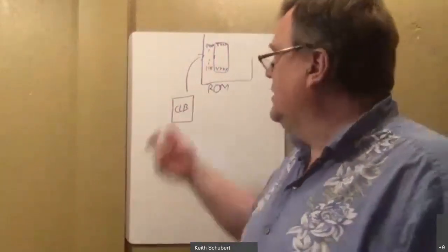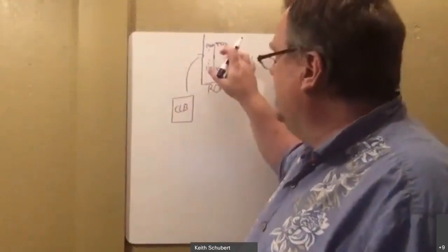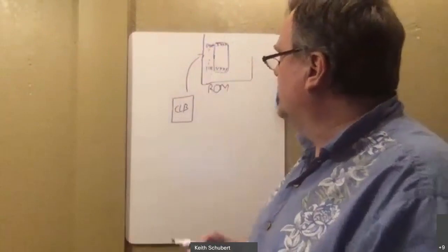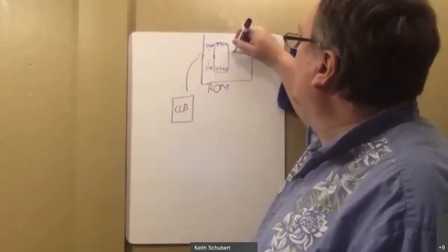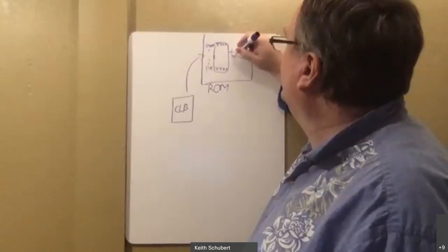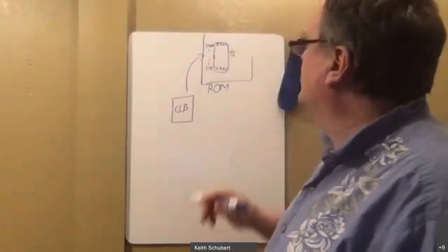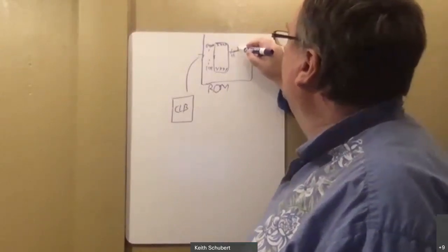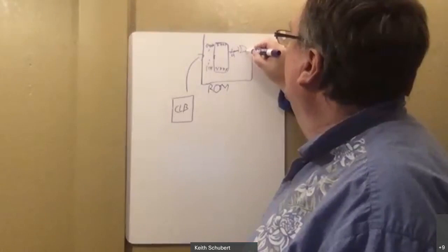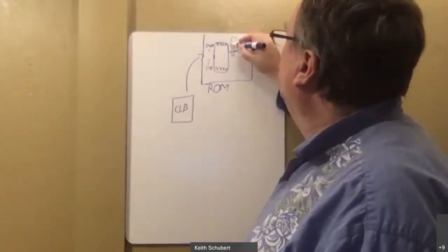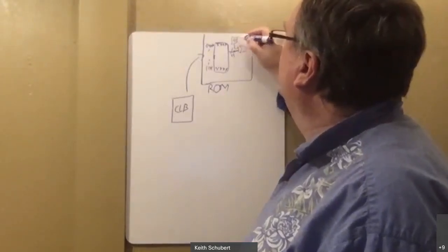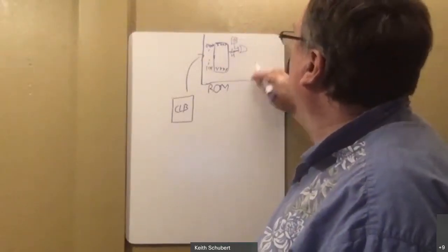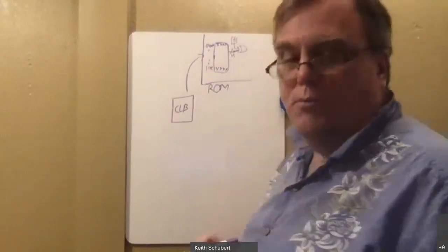It basically takes all the things, calculates all combinations, and uses the inputs as an address, and stores them all. Right. The output of this logic table, which we'll say is another 4 bits, will vary by the particular construction. Remember we have the ability to invert, so they usually go into an exclusive OR, and the other bit is typically set to 0, but it could be 0 or 1 for invert or not invert. That's another thing that you can program.